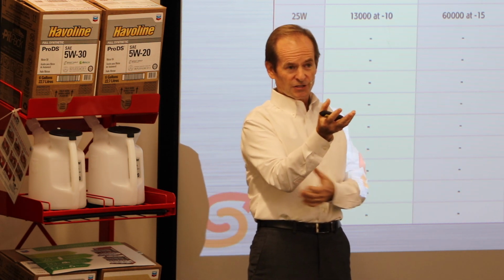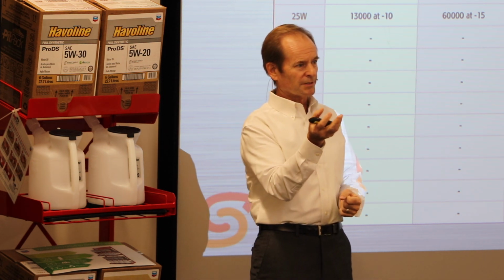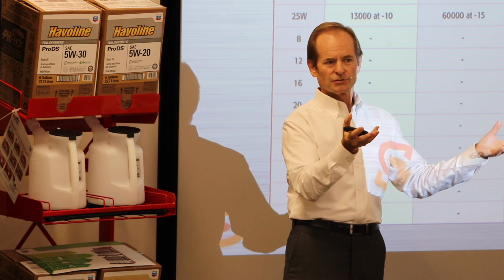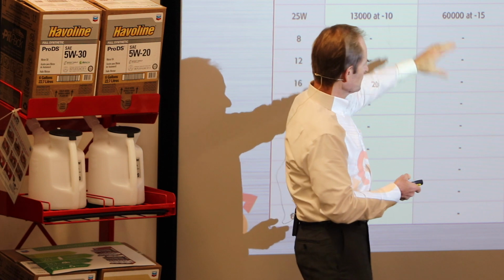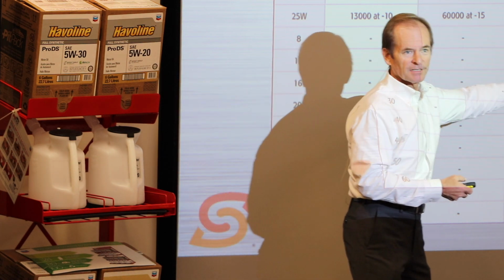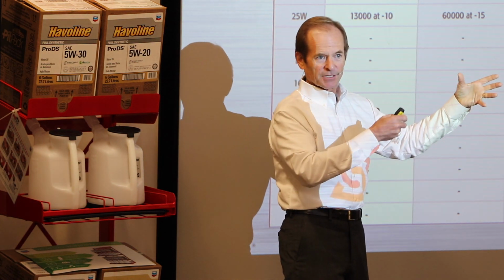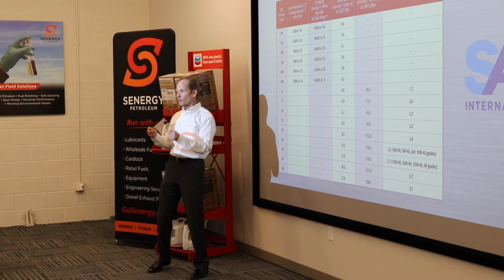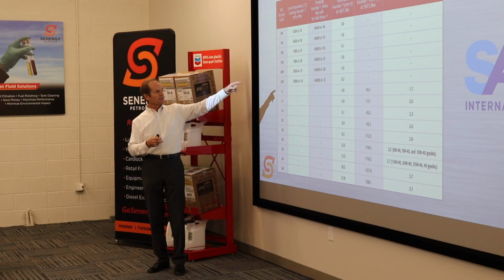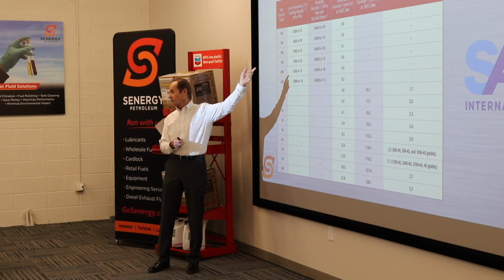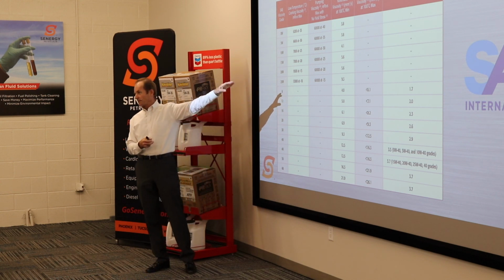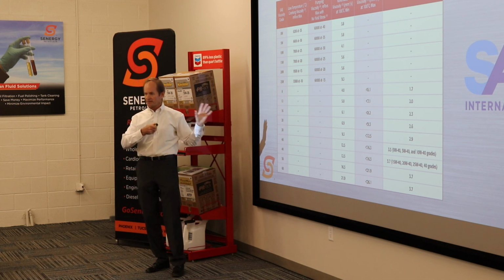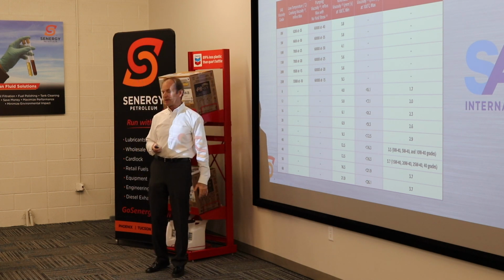It's close to a heated up water jacket kind of temperature. And your 0 F one, well, that's your cold weather one, like you're trying to start your car in Chicago or something like that. And then you go to a chart, and you say, okay, well, it falls within this certain range of a viscosity at a high temperature, then it's a 40. And if it fell over in this other range here in the cold temperatures, that was a 20W. Okay? The W stands for winter. So it was the cold temperature measurement. So that's how the SAE came about.